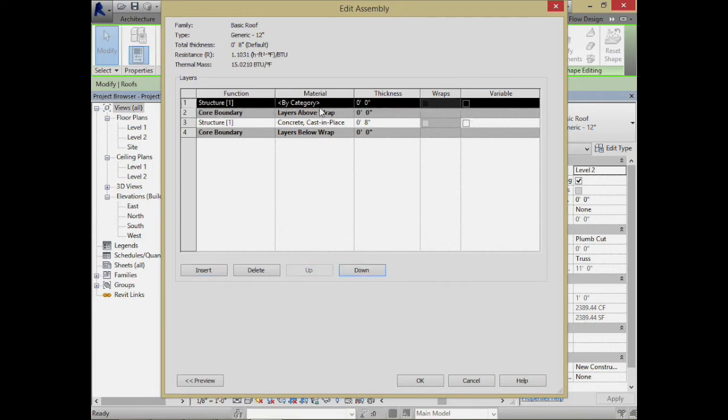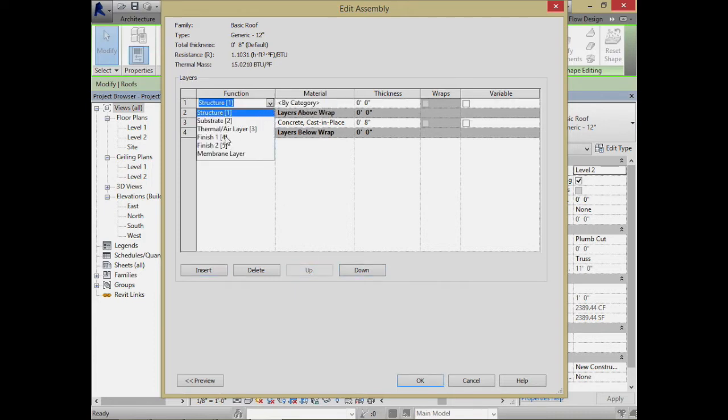So for example, if I wanted to put in some airspace, because I wanted some really clear space where, if I was capturing the water, it would run off and I could get to some sort of water catchment system, I might put an airspace in there, okay? And that could be like 3 inches thick or something like that. Then on top of that, I might have a layer of sand or gravel, some sort of a substrate, and then there'd be some kind of hard layer.